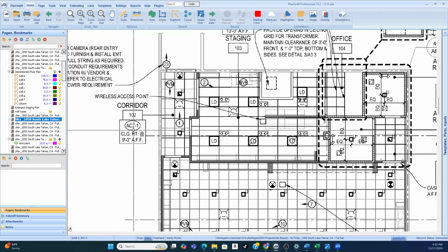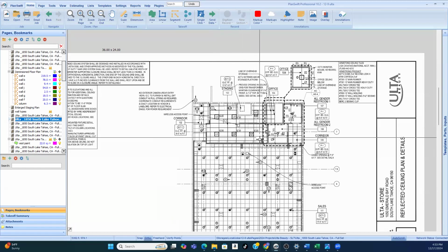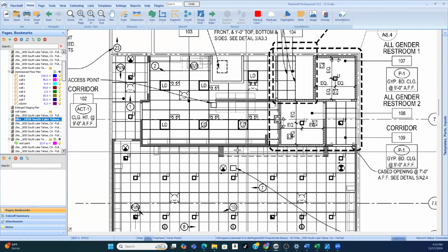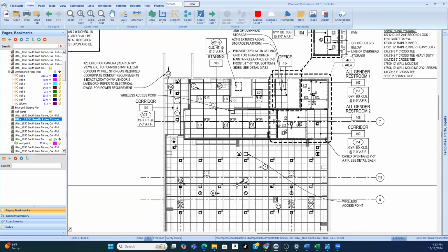And so the job of the reflective ceiling plan is to tell you every ceiling finish and the height of that ceiling. And so if you don't know what the height of the stud should be, well, it's got to go above the ceiling height. And if the schedule, the framing schedule, the legend for the walls doesn't help you, then this will help you.